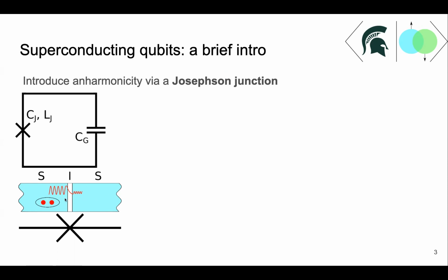There are many fields of physics specifically dedicated to Josephson junctions, so I won't have time to go into all of that today, but really cool systems. And we can use the Josephson relations, which are the constituent equations for Josephson junctions, to write down what the inductance of one of these structures is. And we see it's not a linear inductor. So that means that Lj, for Josephson junction, does not depend linearly on I.